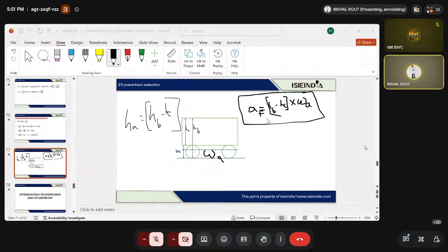Instead of writing those in the table, you can write the values over here under square brackets, the torque values, and you can write the speed values over here. And we'll click on apply. Now what has happened? The lookup table will store this particular thing. Now you have a question, sir, how do you know that the lookup table stored that particular thing or not?